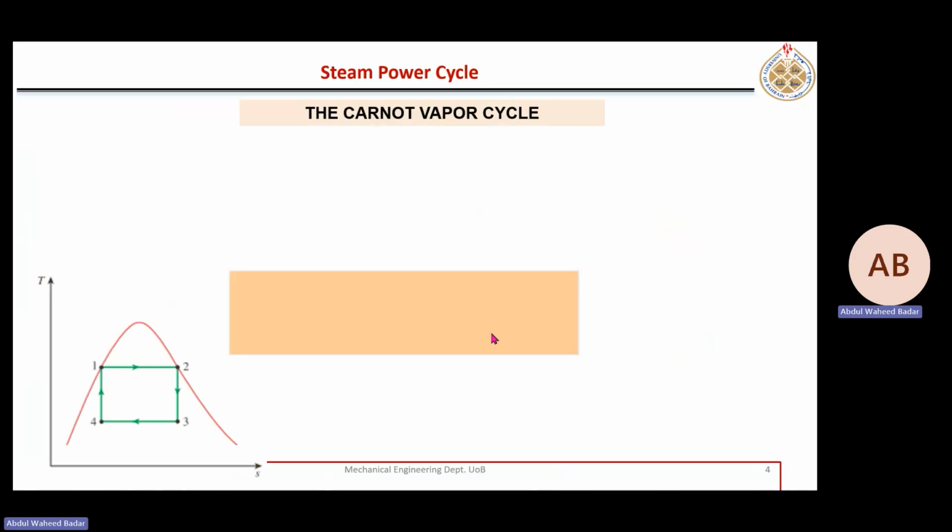Carnot heat cycle: 4 processes, 2 isentropic (pump and turbine) and 2 heat transfer, 1 heat addition, the other heat rejection. All are fully reversible. Then it will give us a rectangular shaped structure, and that we can show for a steam power plant inside the dome. That is possible. Outside the dome, this is impossible.